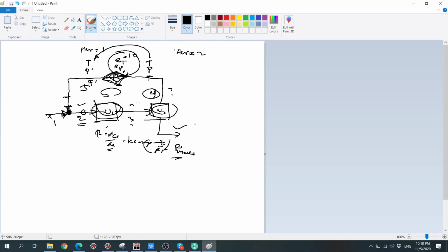Basically, this mass balance helps us understand what exactly is going on in the plant. So you're right, Shafiq. This number should be the same as this number. This is stream number 6 maybe. If this is the plant, stream number 1 in mass should be the same as stream number 6 in mass. If you see some differences, or maybe stream number 6 is lower than stream number 1, there must be a leakage somewhere. If stream number 6 is bigger than stream number 1, there must be some other inputs that we don't know.